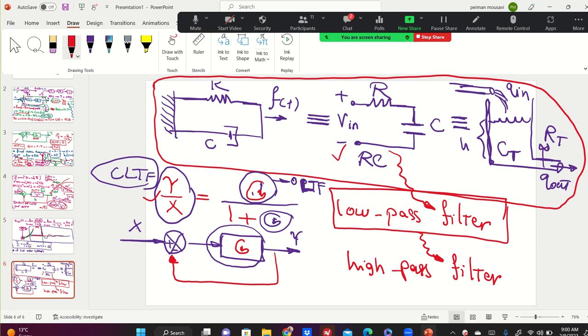The control engineer gets feedback from the output to be compared with the input, to measure the error signal, and as controller, based on the error signal, issues a command to your car, to the room temperature, to the height of the tank, to the voltage of the capacitor, whatever you say, that behaves based on whatever you want.